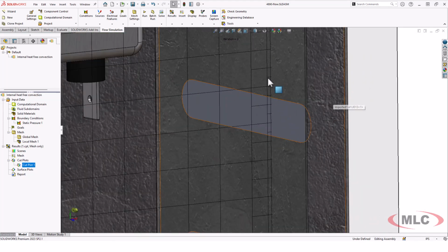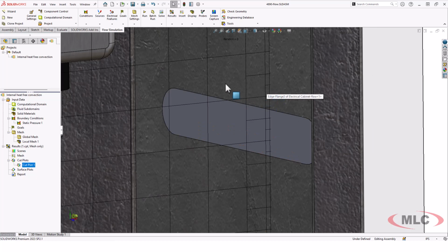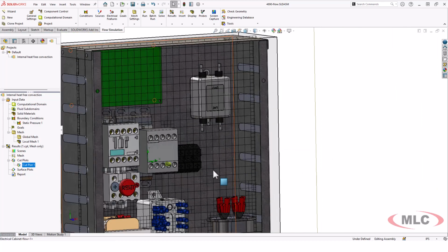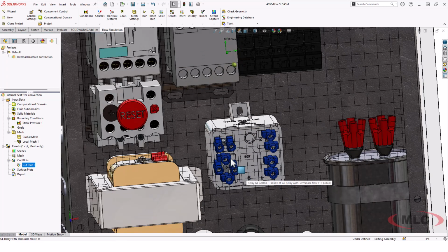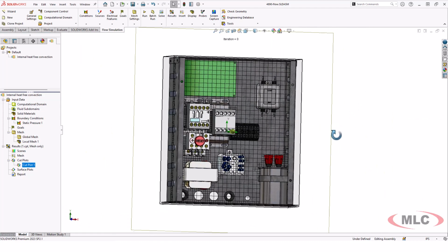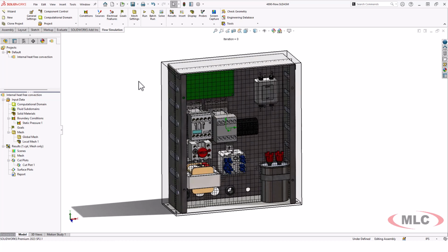These are actually refined along the walls because the basic mesh has to only refine by one level at a time. And so these guys had to be split so they could be split again. That actually could be adjusted, but honestly, this looks pretty good, and I'm not seeing a lot of wasted effort around these areas of detail. So this right here is an efficient mesh that's ready to iterate quickly. And then once I'm done, I can go ahead and unsuppress and add complexity back in, knowing it's going to solve okay.